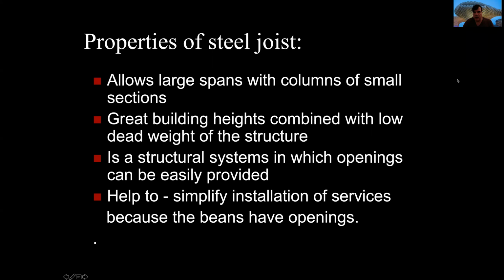For example, if we have a concrete beam and we open a hole, we are reducing the thickness of the beam. All this area in the beam is lost because we have a hole in the middle of it. Only the top section and bottom section will be working.